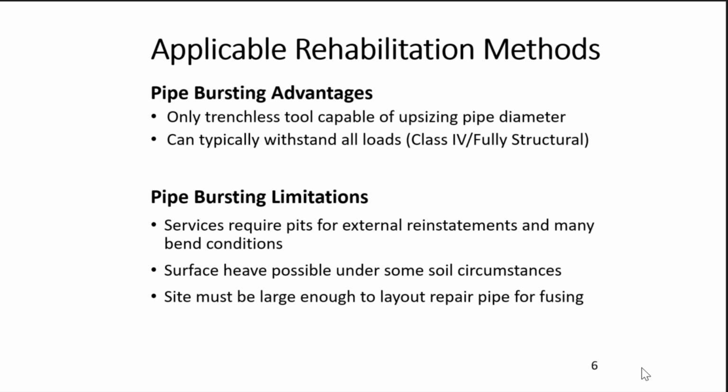All the other techniques we're going to talk about, it's not possible to increase capacity. So it's one of the unique benefits of pipe bursting. And as Ray mentioned, this is really a replacement technique, so you're pulling in a completely independent pipe. It can be designed to withstand all loads, external and internal. So that's a big benefit. One of the limitations, though, Ray, I don't remember if you talked about this: typically, if you have water services coming in going to your buildings and houses, you have to excavate at those to reinstate. So it's trenchless, but it's not completely no trench. You do have to go in and do some service reinstatement. So that's one of the limitations.